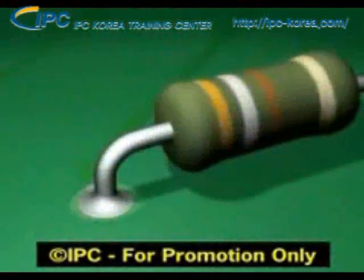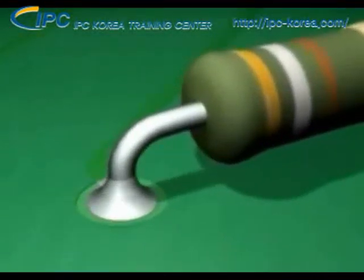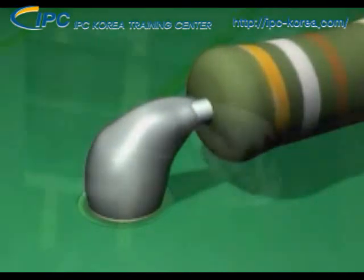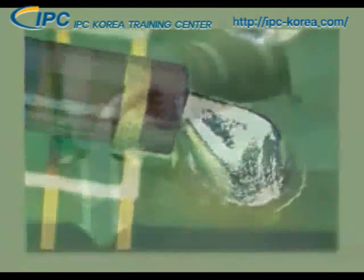The other parameter for the component side of the solder joint has to do with excess solder. The maximum acceptable condition allows the solder to extend up into the lead bend area as long as it doesn't contact the component body. Here's what it looks like when the solder actually touches the component.